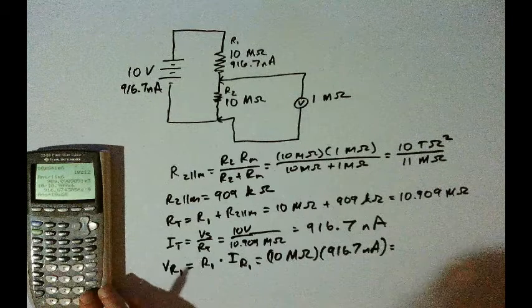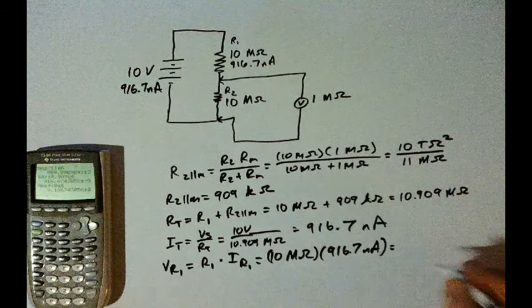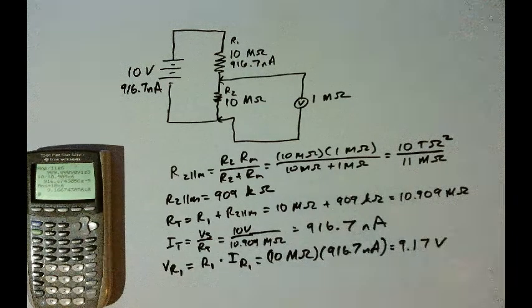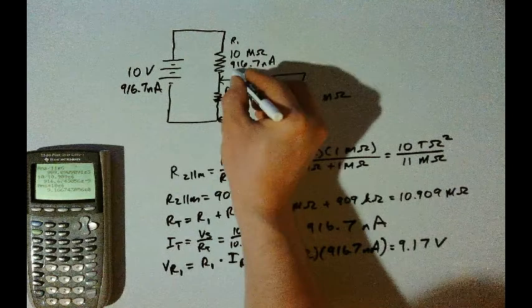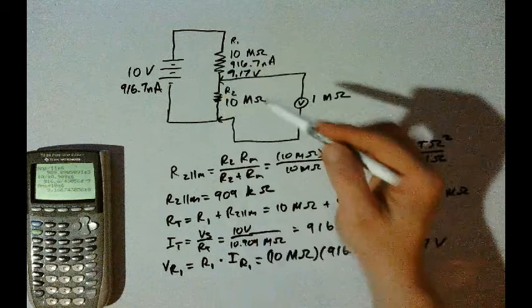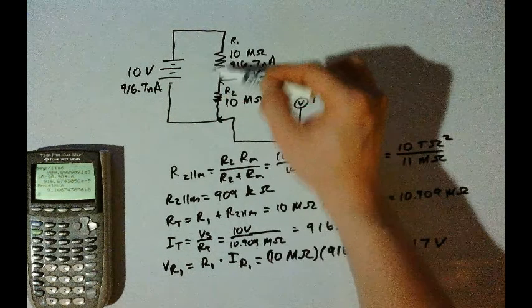And again, it doesn't matter what path we take here. If we go through the voltmeter and then R1, these two voltages add up to 10 volts. Or these two voltages add up to 10 volts, either way. And so that is the answer to the question. The voltage drop on the meter will be 830 millivolts.